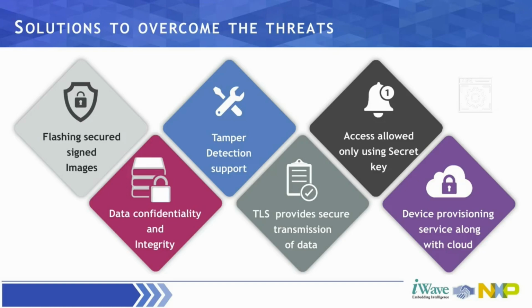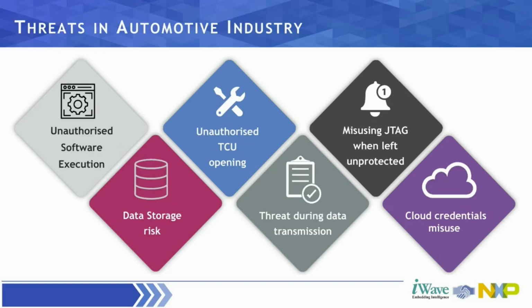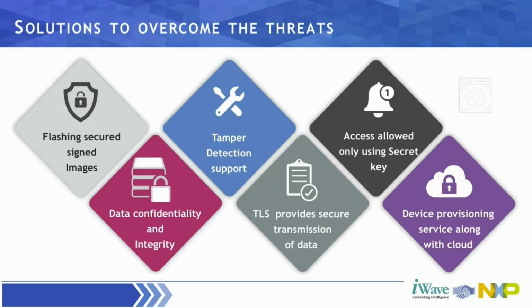Tamper detection: having the pin of the processor connected to the enclosure, you are made aware of any intrusion into your mechanical or the complete enclosure. And from your cloud connectivity point of view, you have the TLS libraries, your secret keys, or the device provisioning with complete tokens. With these solutions to solve the problems listed on the previous slide, we have been helping various automotive OEMs secure the ECUs, and this is just an example. The same concept can also be applied to your industrial or medical systems.